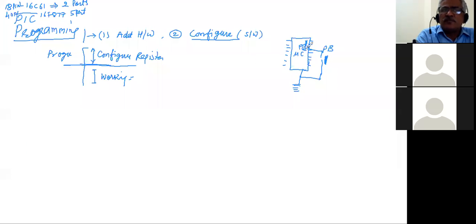So activating the pull-up resistors, now if you read the status of this particular pin, you will be reading the status as equal to 1 because this has been pulled up high. And when you press this particular switch, this high is grounded and you will read the pressed key as equal to 0. I hope I am clear.